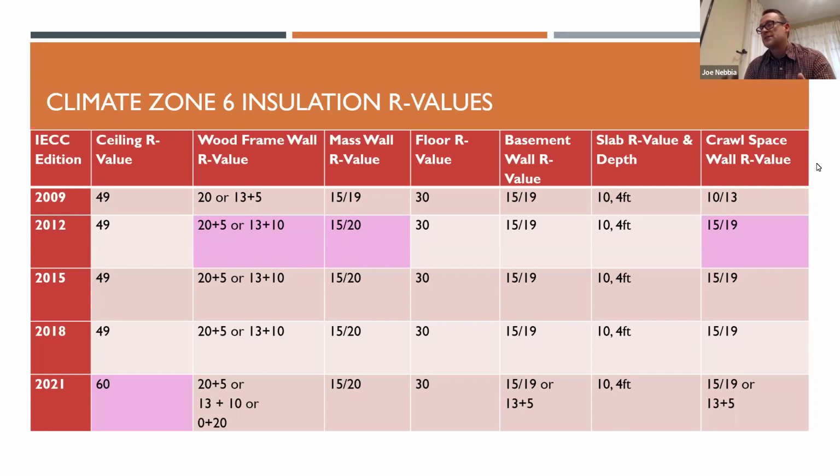So let's talk about ceiling R value for a moment. That column there is just going to give you an amount of insulation. So R60 or R49, so that's labeled batts or inches of blown in insulation, and it's calculated by its tested R value per inch. The R60 is obviously a big jump over R49.